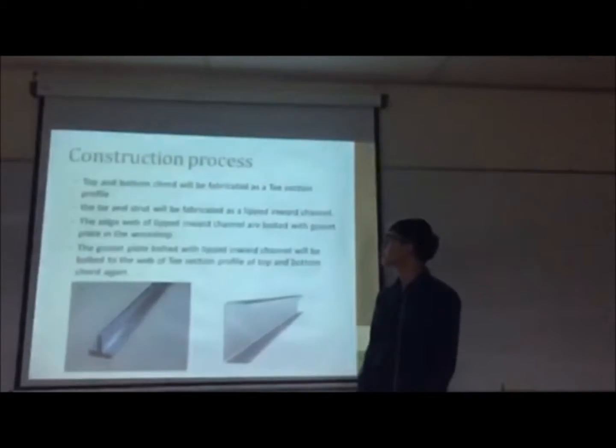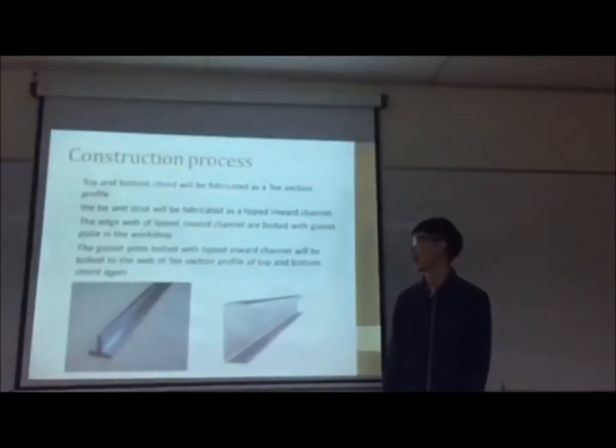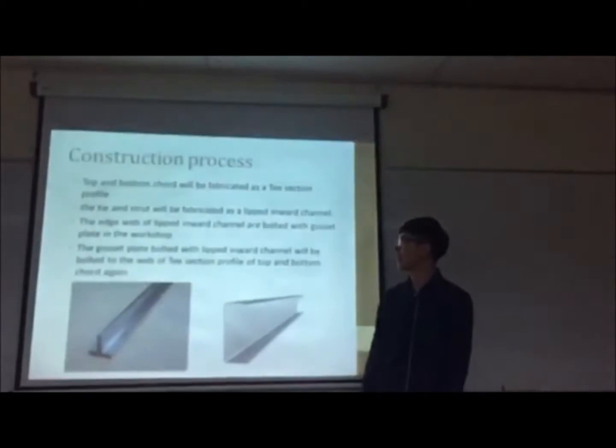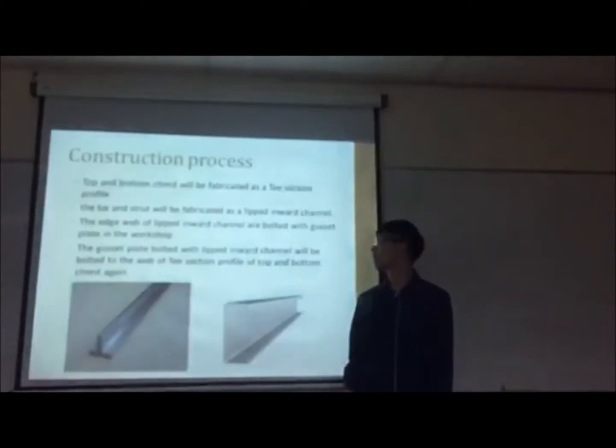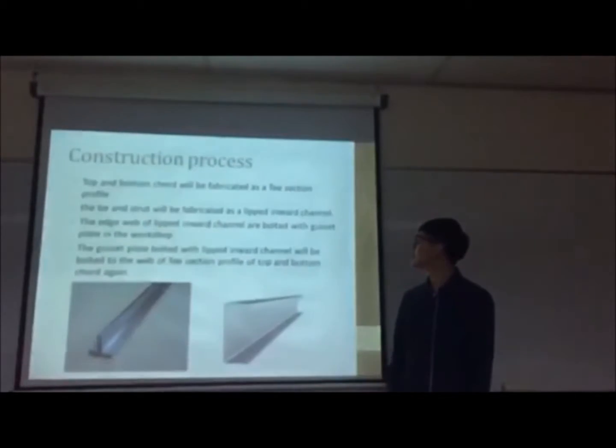The top and bottom chords will be fabricated as a T-section profile, and after that the tie and strut will be fabricated as a lip-inward channel.